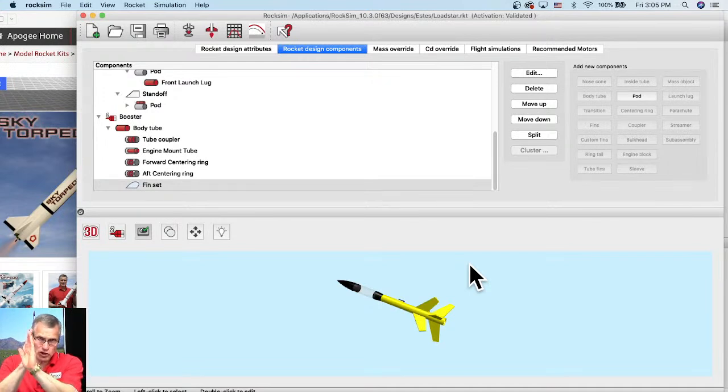If you want more stability, then putting the fins like this would be preferred. And the reason for that is the front fin is creating drag and it's creating turbulent flow, and by moving the other fin outside of that turbulent flow, that other fin becomes more effective.